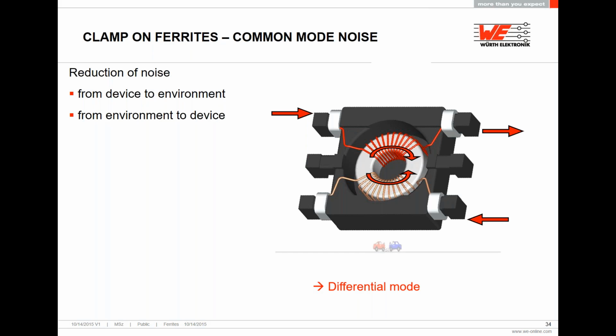And then the differential signal has to go back to the source, which creates another magnetic field according to the right-hand rule. These two signals cancel each other out, so the animation is giving you a visual representation of this cancellation.